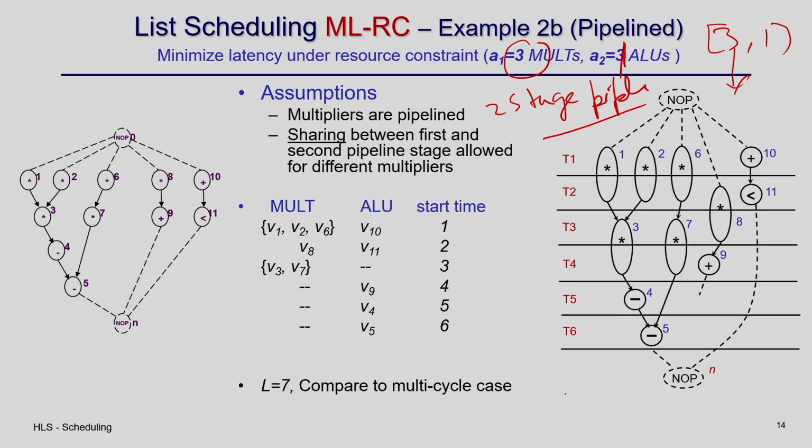So, just to finish, if this is the multiplier, it has 2 stages, I have a pipeline here. What I am going to do is, in the first clock I am going to give, say, A1 and B1. It will do the multiplication and put the intermediate results into, say, R1, and in the next clock I am going to give A2 and B2.